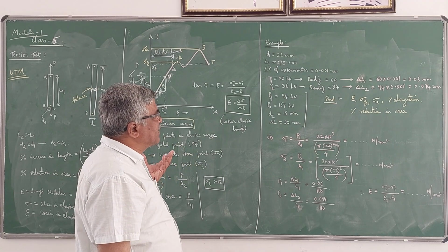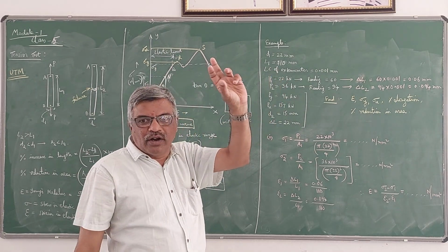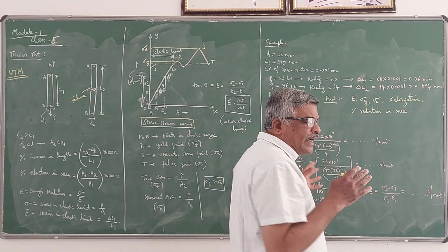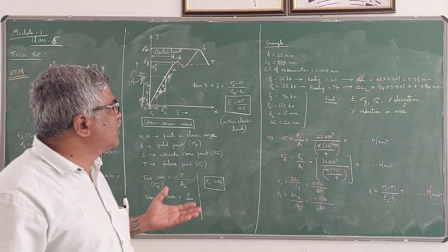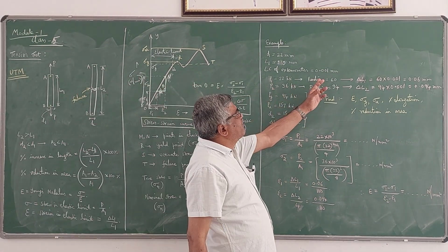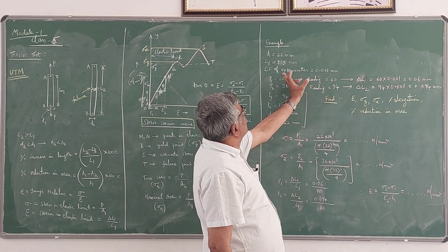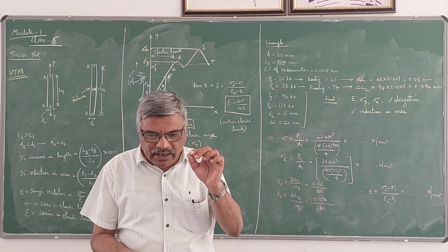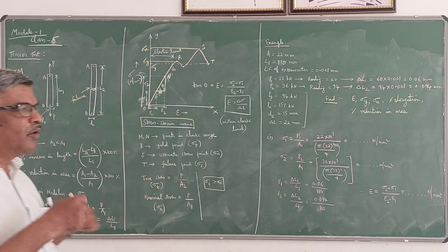The extensometer will have some least count, just like your slide calipers and screw gauge. Least count will be there for a given extensometer. Least count means the minimum dimension that can be measured using that particular instrument. I have taken a problem here, later I can explain that. Using that extensometer or dial gauge, we can measure the increase in the length, and in that UTM there is a load indicator.